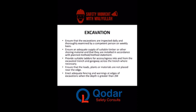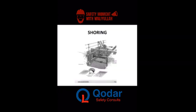Some soils are very soft. When excavating, you see the excavated soil backfilling inside. To avoid such, we want to ensure good shoring by using timber or some metal. Some organizations decide to use piling sheets. Whichever works, shoring should be suitable, and it should be in accordance with the method statements. We also need to ensure that there is enough access and egress with a suitable ladder, and there should be a warning sign for any excavation that is below 2 meters.